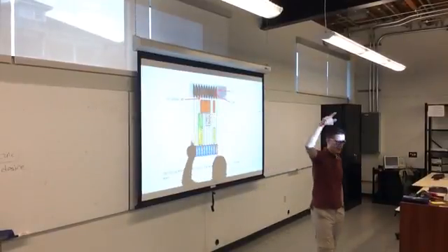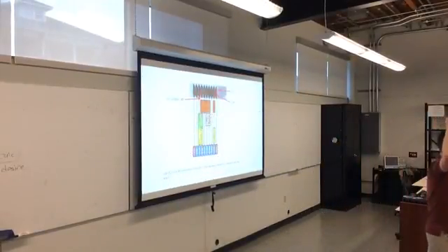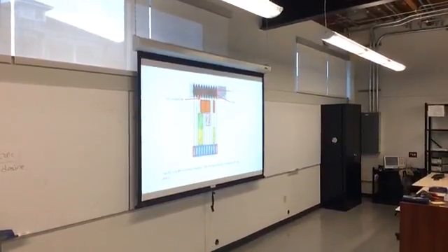Try this lab again this year. I spent 2 days on it. Nothing worked. I would get data, it's bad data. I changed out chips, I moved to Arduino, I tried different stuff. The one thing I never changed was what pins I was communicating on. So if you all did that, I would say, oh my God, how do you not change your pins? Just try it out and see what's different.